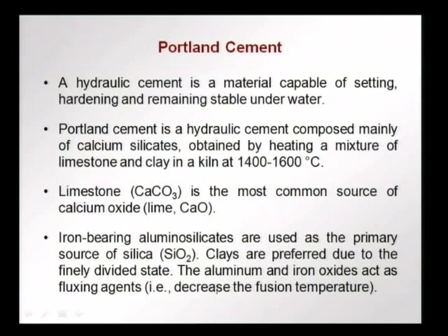In some cases in India the limestone itself has a very high content of silica, and there clay is not necessarily added, but in other cases where the limestone is purer and does not have much silica, clay is added, because clay in its finely divided state can mix well and can be processed easier.